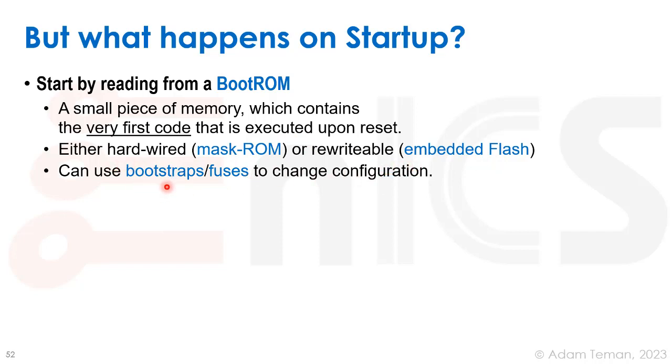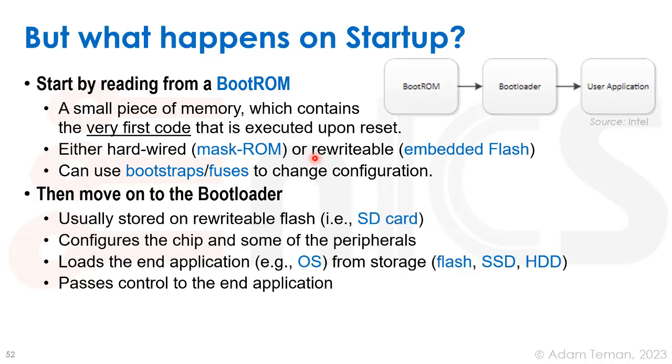Okay, we can also use all kinds of bootstraps or fuses to change simple configurations to make differences between chips. But in general, we can consider this BootROM as something that's really hard-coded and not changeable. But what the BootROM does is move on to the bootloader.